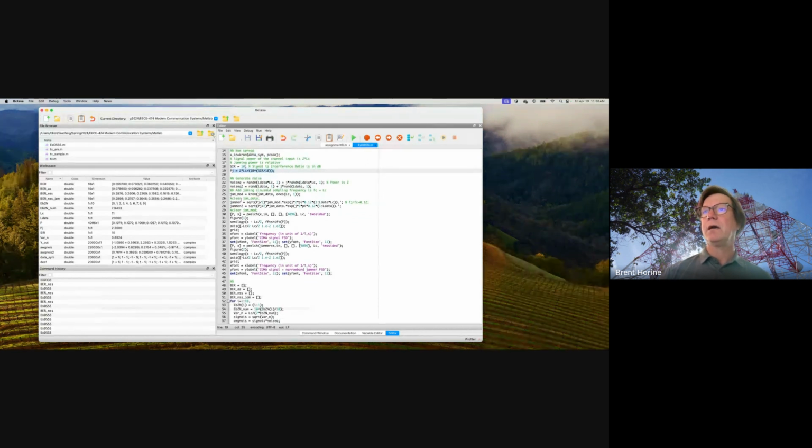So here we generate the jammer, and there's an adjustment to the frequency of this 0.12, and then we're just generating a complex exponential here. And then adjusting the powers for that, taking the power and converting it to an amplitude type of thing. Then